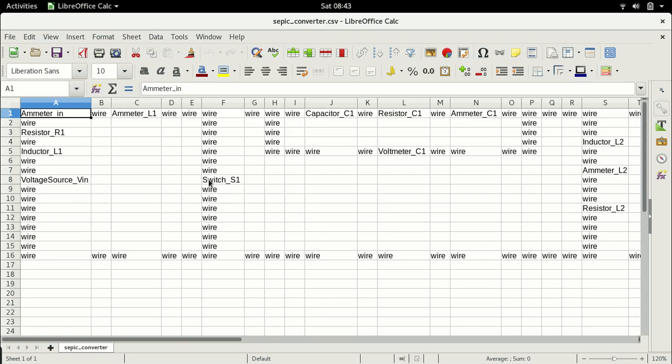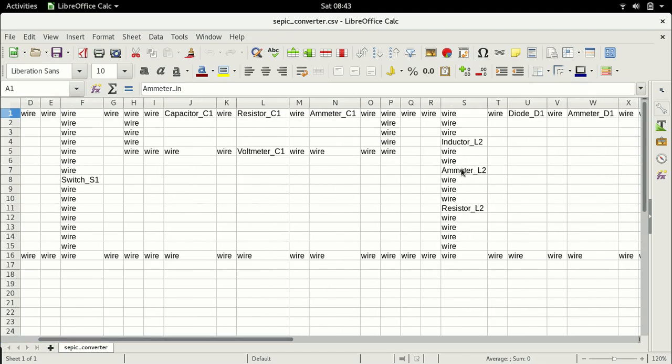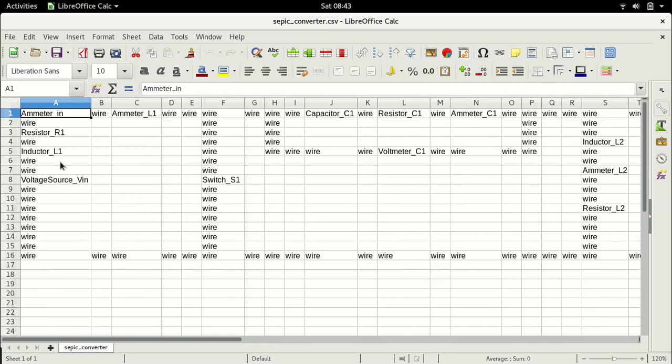Right? And it is during this short period of time the current through inductor L1 rises. This is when the inductor L1 is charged by the input voltage, and this inductor is also being charged but by the discharging capacitor. So you need to understand that the primary source in this case is this input voltage, and therefore it is this input voltage's ability to charge the system that really impacts the level of the inductor current.